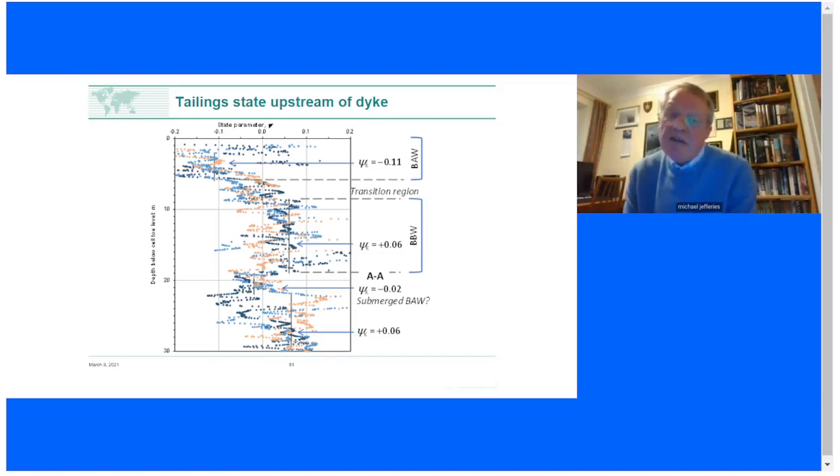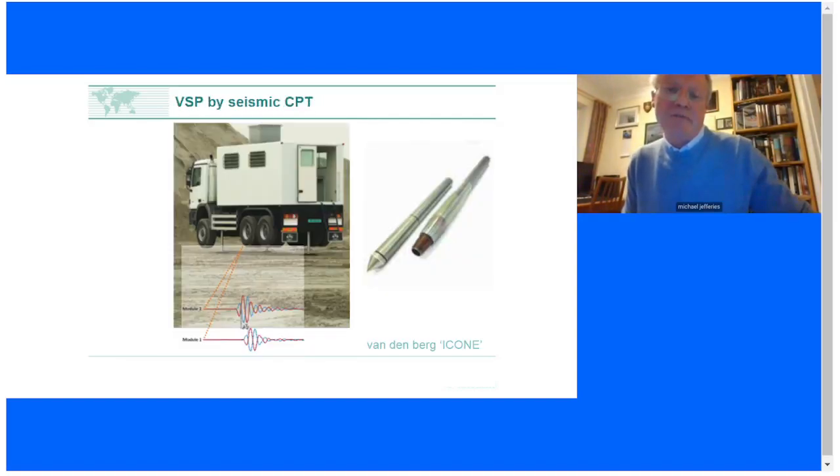With this set of choices, we actually calculate 4 meters of settlement versus 5 meters measured. I think if I look at this now with hindsight, I should have taken a slightly more contractive pick of the state parameter at the bottom. But this is something you have to do yourselves when you look at your own case histories. We're giving you a very mechanics-based approach, but at the end of the day, there's still a good chunk of engineering judgment as to what is appropriate. I'm sketching out for you now the basis on which you make these judgments.